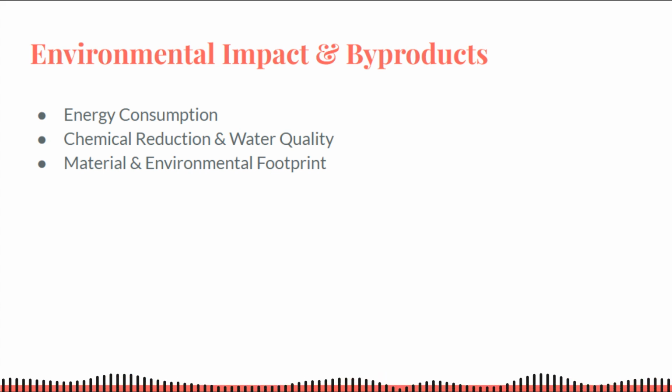Ozone itself reverts to oxygen, leaving no persistent chemical in the water. Hydroxyl radicals from AOP are short-lived and likewise do not remain to form residues. Consequently, pool water treated with ozone AOP tends to have lower levels of chloramines, trihalomethanes, and other disinfection byproducts that can be harmful to swimmers and corrosive to equipment.